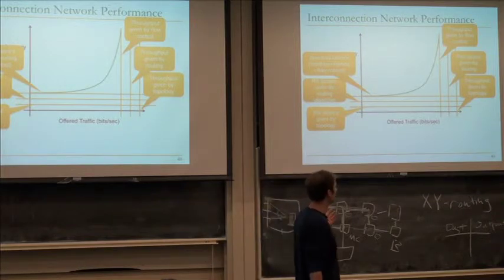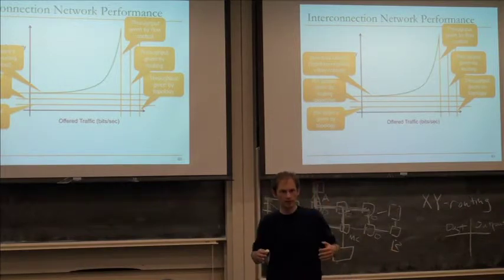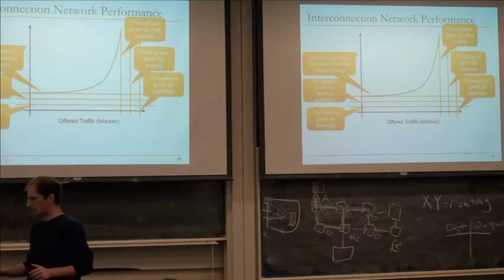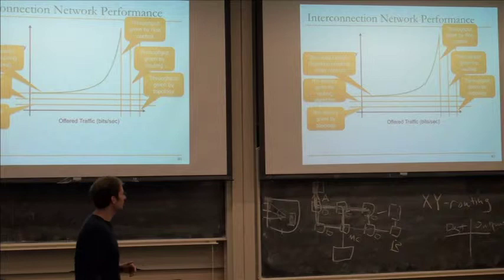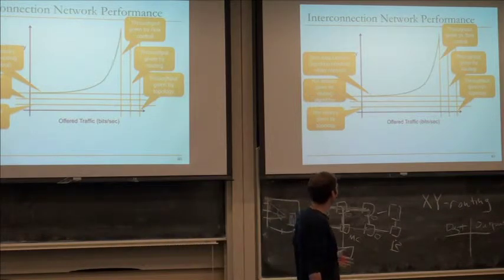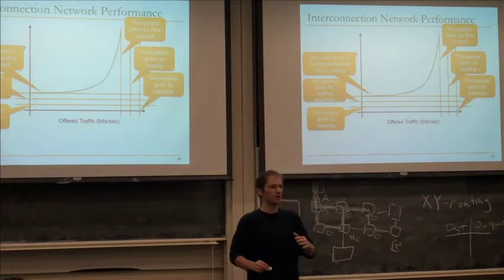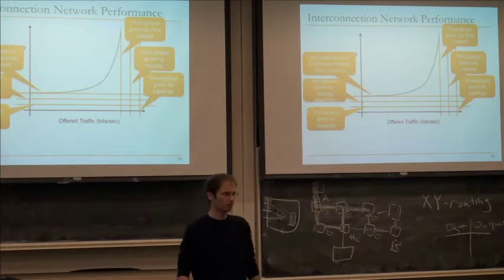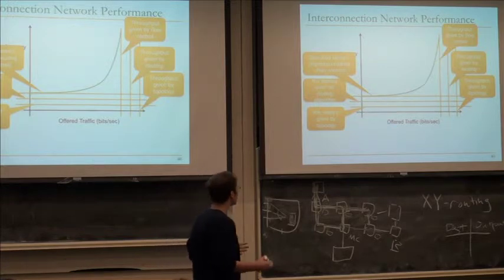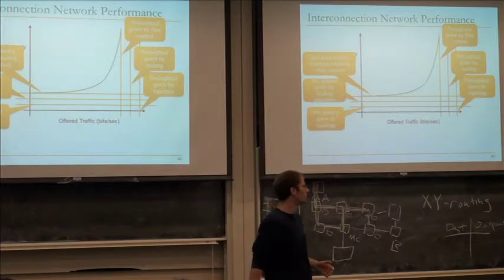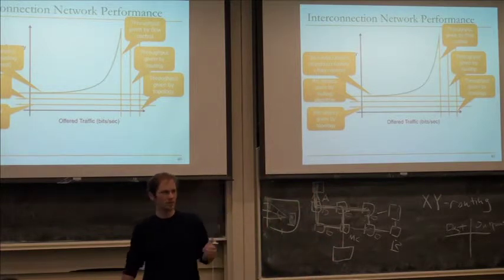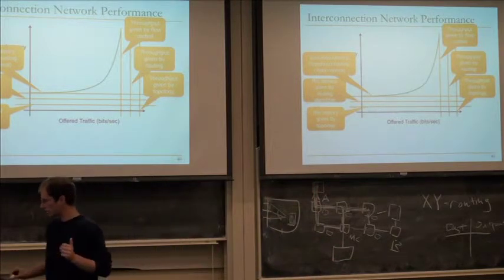Once we consider things like buffer allocation and the way we arbitrate for contention, there's some realistic upper bound that we can achieve. Typically in a buffered network, this saturation point is something like 0.6 or 0.7 flits per node per cycle, where one flit per node per cycle would be the optimum. So if you design your buffering strategy well and you design your routing well, you can get fairly reasonable efficiency, but it's not going to be perfect efficiency because you have these overheads.